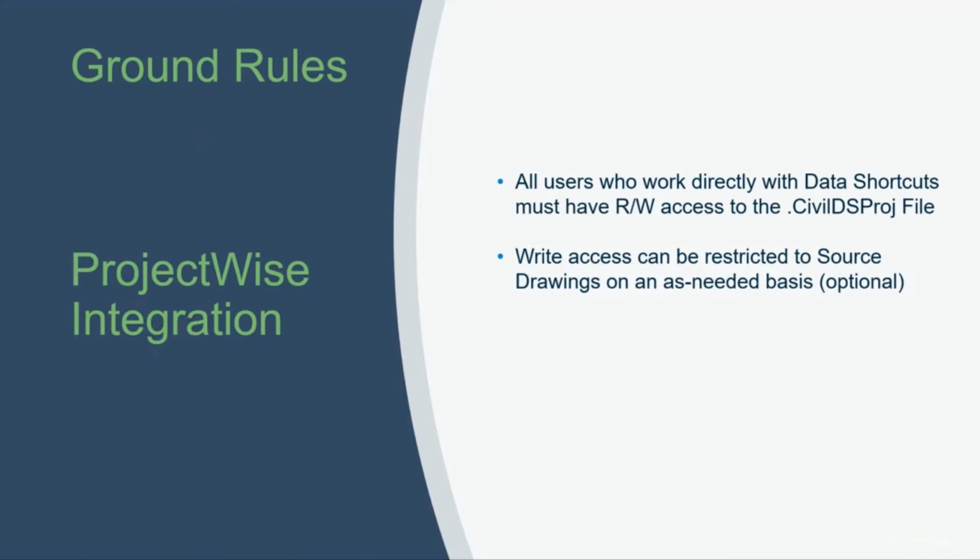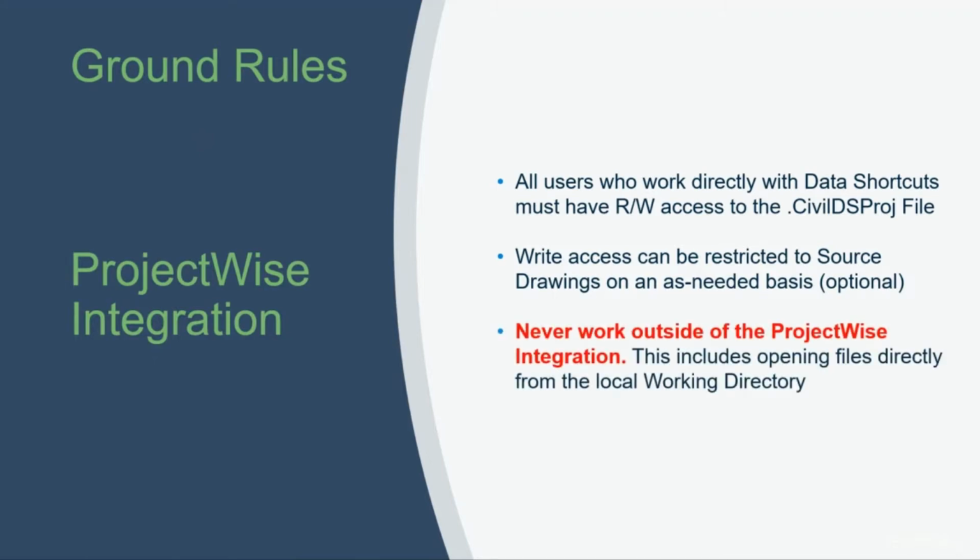The last ground rule, and probably always the most important thing that we need to advise users of, is never work outside of the ProjectWise integration. That includes going through the back channel and opening files directly from those DMS folders. That's especially true when you're working with files that have relationships with each other. So XREF, definitely. If you attach an XREF behind the integration, ProjectWise doesn't know about it. It doesn't add it to the logical set.